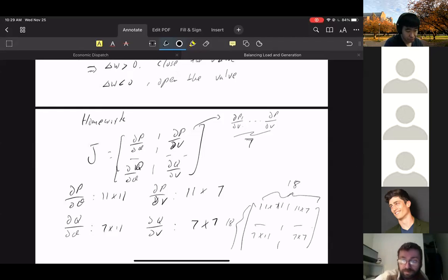When we build a mismatch equation, how many mismatch equations do we need? If the Jacobian is 18 by 18, you have 18 mismatch equations, and you multiply the inverse Jacobian onto that mismatch. So we do the mismatch equation from P2 to P12, and the Q is just Q4 to Q9 and Q11, because we don't know the PV bus Q. Yes, that's a good question.